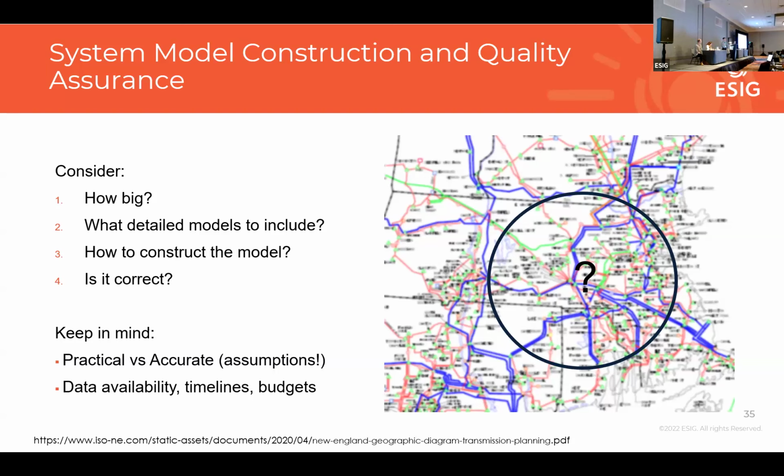And then there are some realities that we have to deal with when you're putting this model together. We don't have all the data that we would like to have. We don't have test reports of every transformer that's going to be inside of your system necessarily. So you're not going to be able to get the saturation curves right for every transformer in your PSCAD system. There's timelines involved. You don't have an eternity to put together the model either. There's these external factors that you have to deal with. There's budgets involved, so you can't have 10 engineers working on this at the same time, and it will quickly eat up the budget.